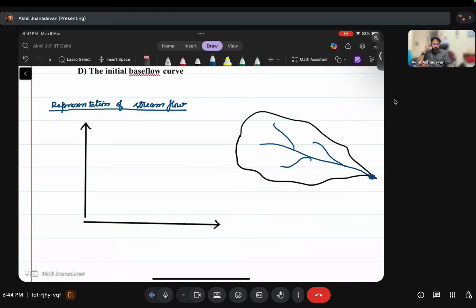When a precipitation happens, the water is used to satisfy all the storage components. Once all those storage components are satisfied, it starts slowly ponding over the surface. When the ponding depth increases, sheet flow starts. This sheet flow is called overland flow, and the sheet flow goes to the channels, which form a network of channels. Finally the stream flow is formed and reaches the basin outlet, right?